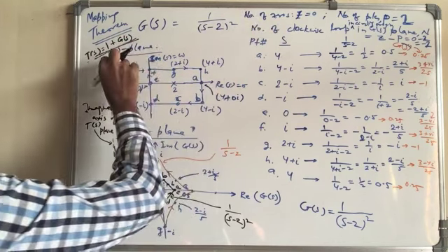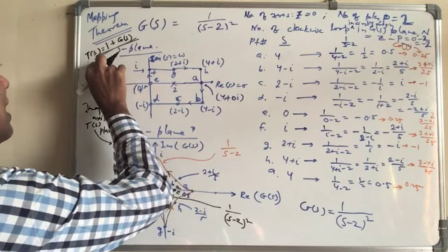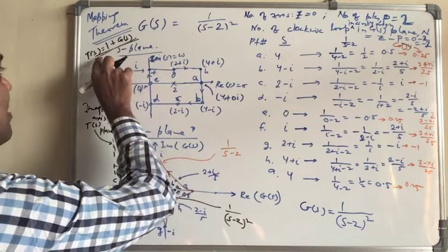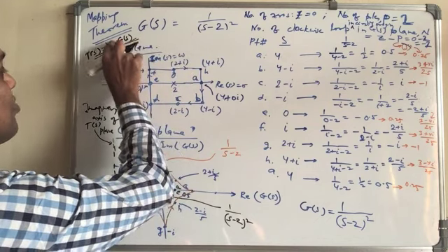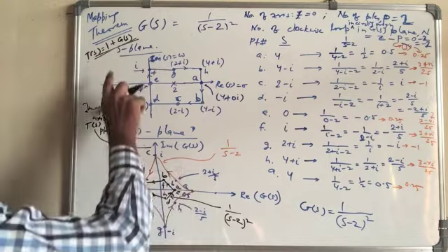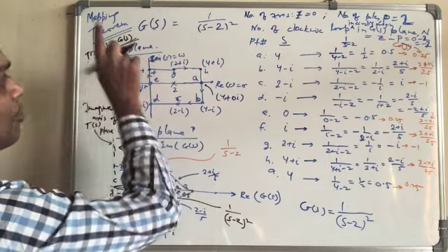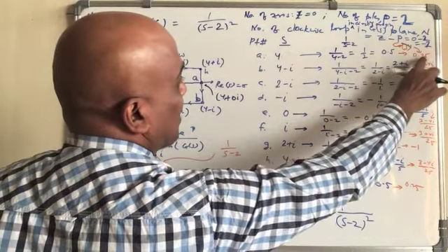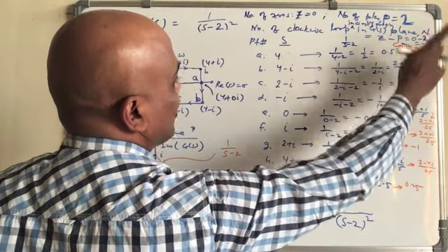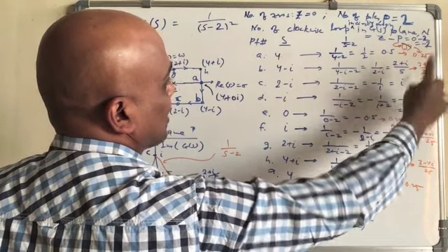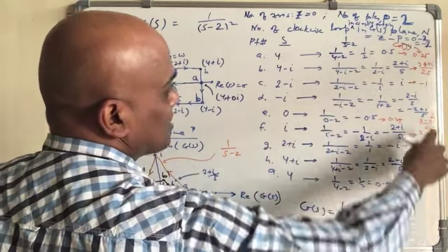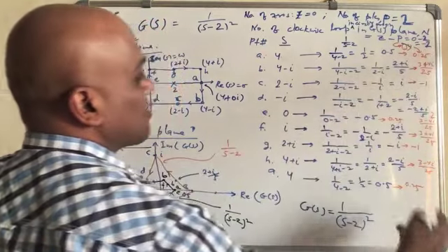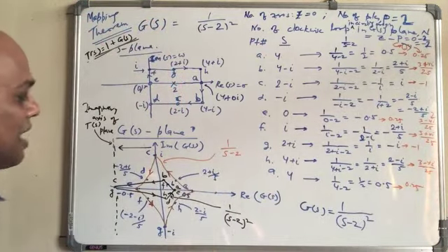So we want to know how the mapping looks for the closed loop system, and for that, the mapping of 1 plus G(s) is important. How can we do it? You just add 1 to the value. So 0.15 becomes 1.15, and this becomes 0, for example, and so on. We just add 1 to all of them and you get the T(s) value.